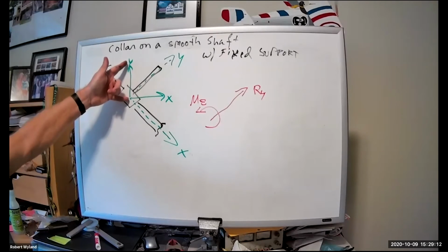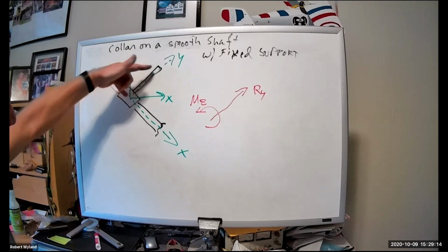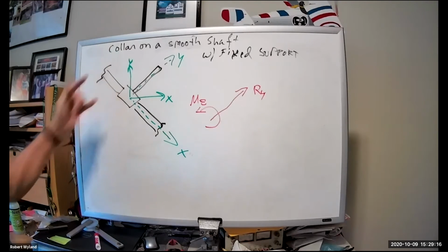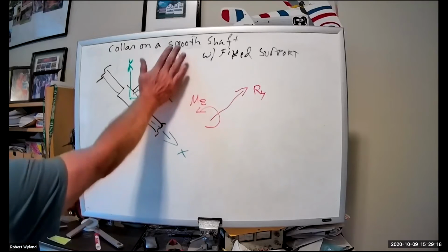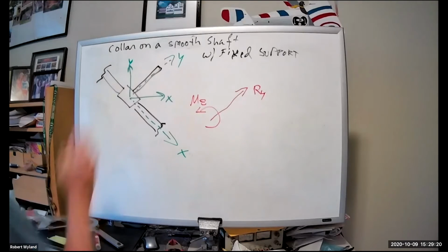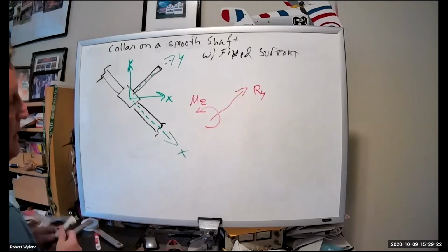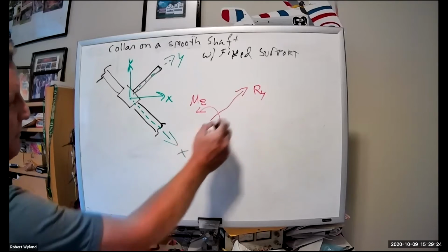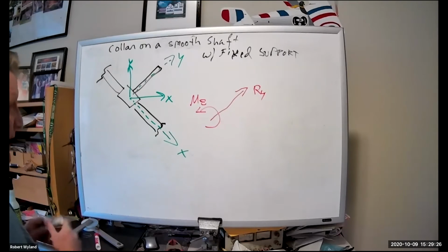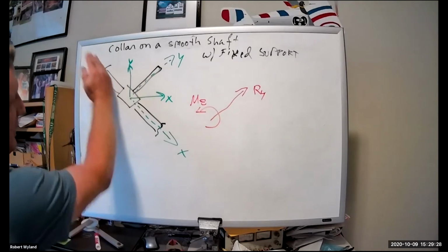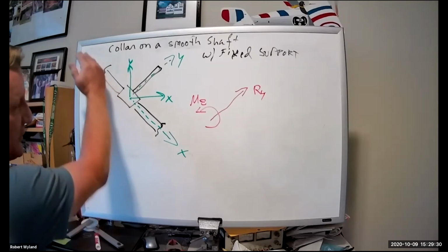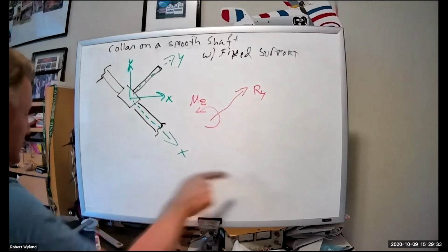And then of course here, the only portion that would exist is this, and there would be no X component. But the best way to do this, like I said, is to rotate and draw it this way. And you'll know this angle in your problem, so you'll be able to figure that out. So draw it like this, orient it along the actual axis of the shaft, and do your reactions that way.